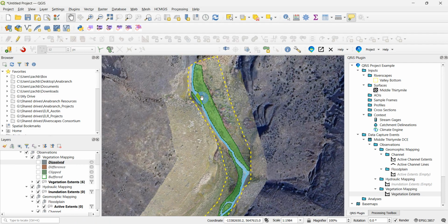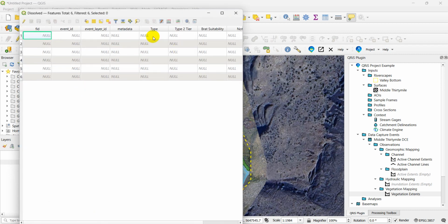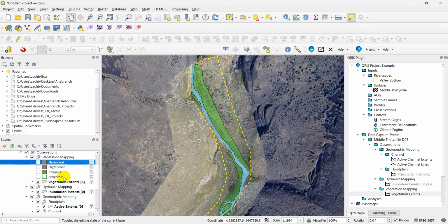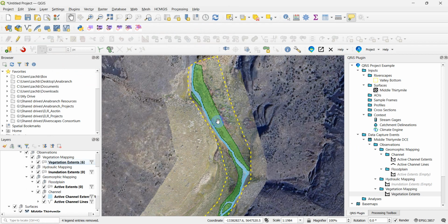If you wanted to name it differently, so for example, if you had also non-riparian vegetation, you just go in here, select any of these fields, for example, and then just type in riparian or non-riparian, and then once you use that widget to import from a temporary layer, you'll just make sure that it aligns to whatever your naming classification is for that temporary layer. So we'll just remove those temporary layers for now. We don't need them anymore.